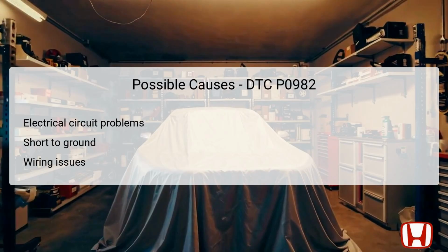Additionally, if there are frayed wires or damaged insulation, these can also contribute to electrical failures. Therefore, careful inspection of the associated wiring harness and connectors is essential in the troubleshooting process. Understanding these potential causes can guide technicians in effectively narrowing down the fault and implementing solutions.